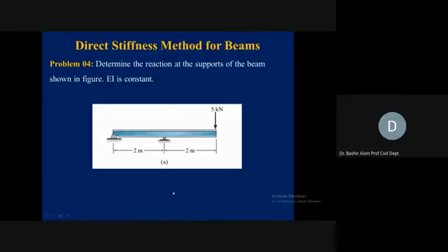If somebody asks you for the displacement in the middle of these supports, that also becomes a node, because you have an interest there in how much the displacement is going to be at that specific point. If somebody asks at 1/3 between the supports, that 1/3 point also becomes a node. But for the solution of the problem here, the minimum requirement is 3 nodes and 2 elements. The rest of the values you can then find out with the help of interpolation.